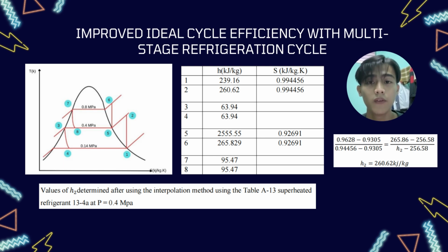For the value of enthalpy H1, we're going to refer to the pressure table at 140 kilopascal, and we will take the value for Hg.